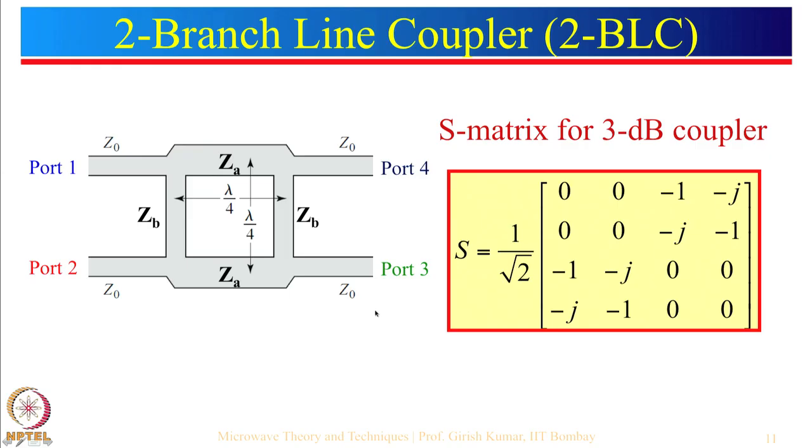So now let's see how we do the analysis of this. This is nothing but a 4-port problem, and this 4-port problem is simplified by using symmetry. We can see that there is a symmetry along this particular axis. By using the concept of symmetry, as I mentioned for the coupled line, what do we do? Instead of feeding only port 1, with value, let's say, 1 and 0, 0, 0, we think about feeding plus 1 here and plus 1 there, which will be an even mode symmetry.